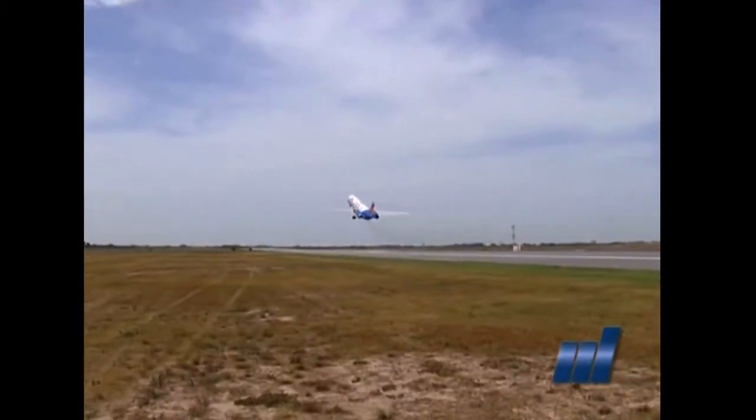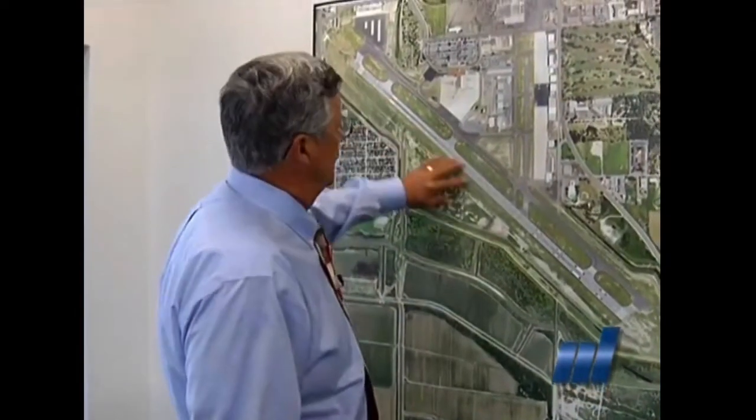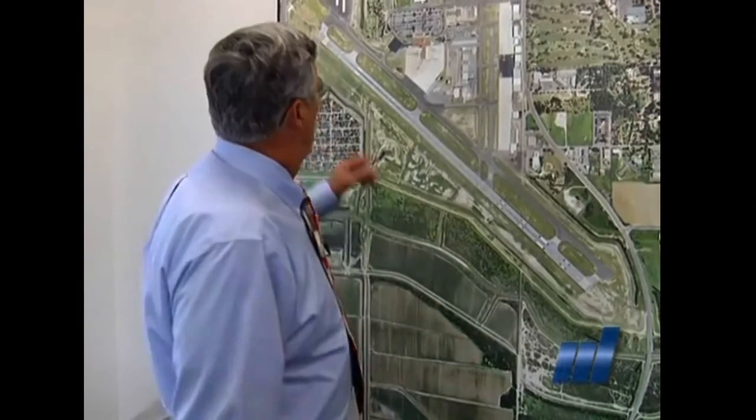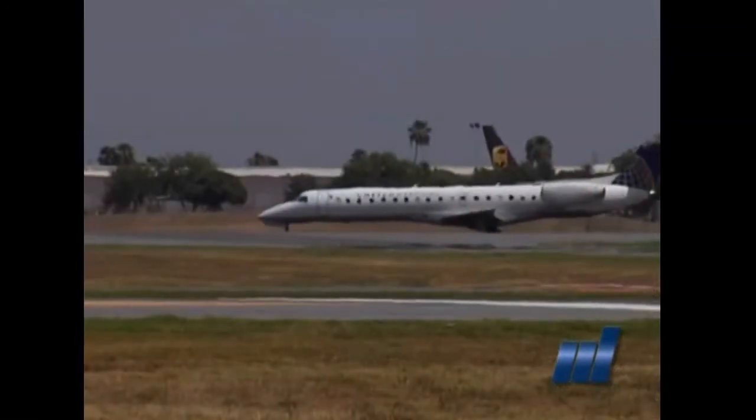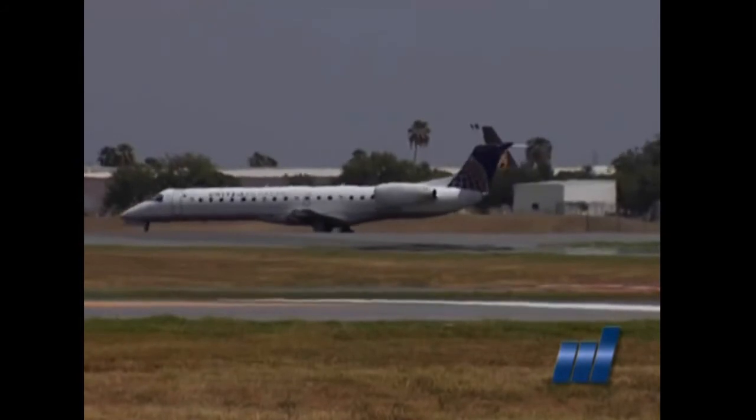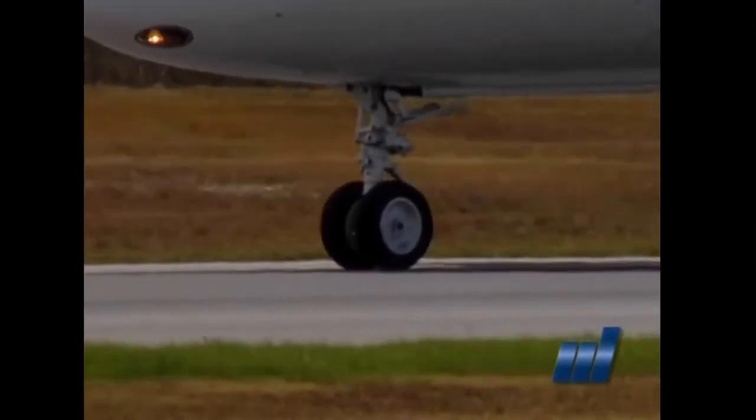One is an alternative that allows us basically to use what we have here, do declared distances, and spend a couple million dollars. We lose a little bit of runway. We go down to, on runway 31, 6,940 feet instead of 7,120. On runway 13, we keep the 7,120 as far as takeoff distance available, but we lose a little bit on landing distance available. And that's a relatively inexpensive $1.3 million fix.